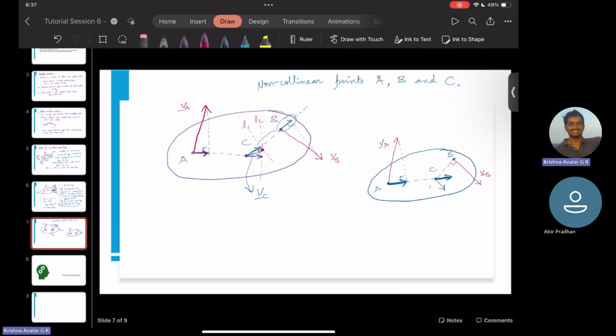And what we do now is draw a line perpendicular to this vector at the tip, extend it, let it go endlessly on both sides. And then along this same direction, we allow it to extend parallel to VB till it intersects. It intersects here, this line. It touches the line. And this is our velocity VC. That's how we were able to obtain it.